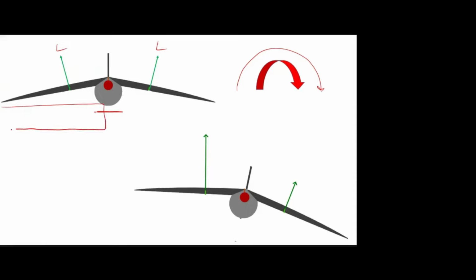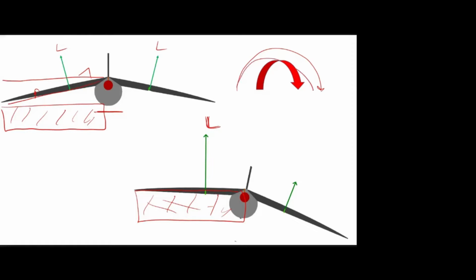This is the reference area that created the lift. Okay, that is this length. But now, because of the side slip, this is the reference area which produces the lift. Compared to this length, it is more. So here the area is more, lift also more. Already the aircraft is side slipping to the right. Now this also produces an additional moment, so the aircraft will easily roll.